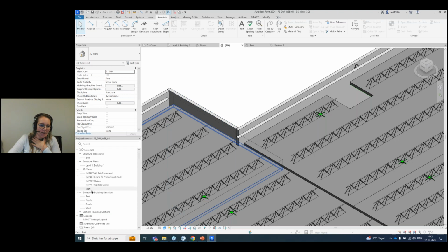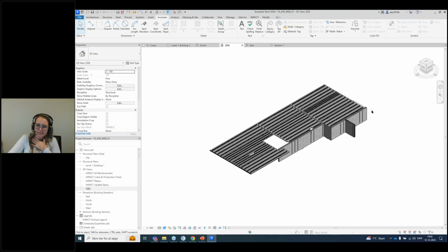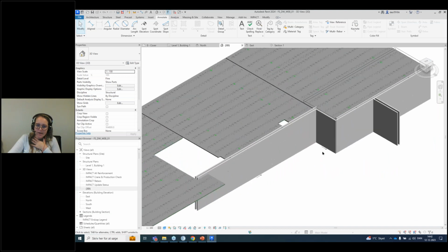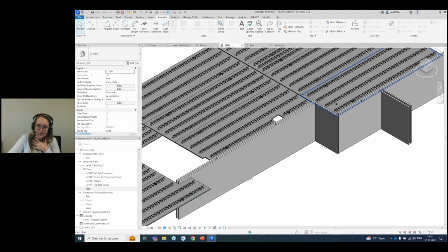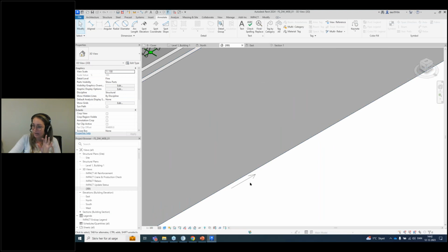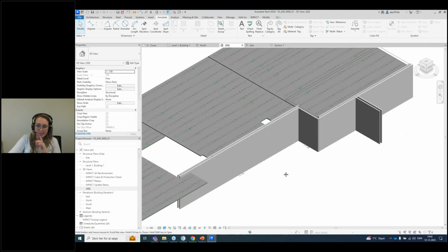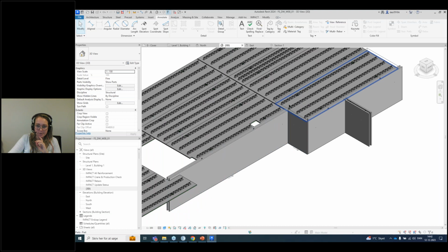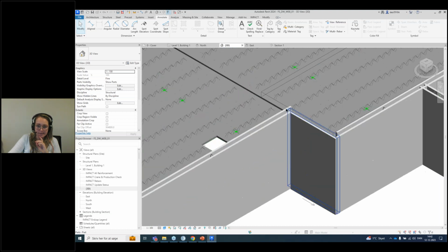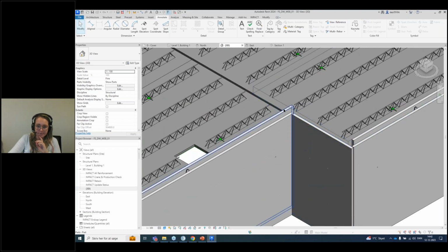We need to figure out, if we go to the 3D view again and see it from here, I can identify, probably you wonder how you can find out if it's panel 1 or 2. Well, you can do this with the help of the arrows. The arrows are always on panel 1. So that's why we need to go and edit panel 2.